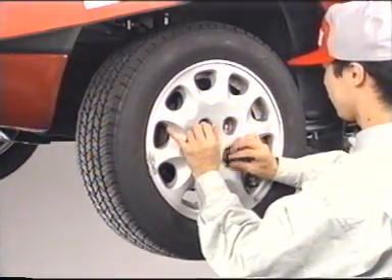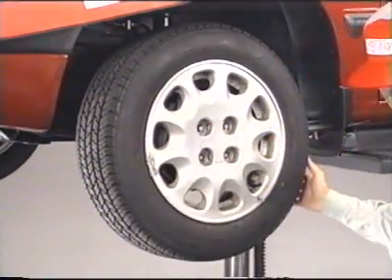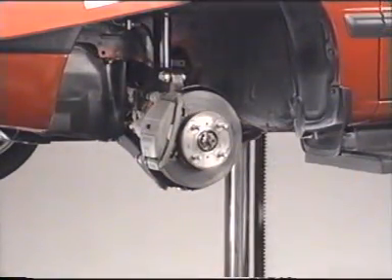Worn-out pads or oil or grease on the lining could cause inefficient braking. If the lining pad sticks, brake grab, squealing, or chattering could result.